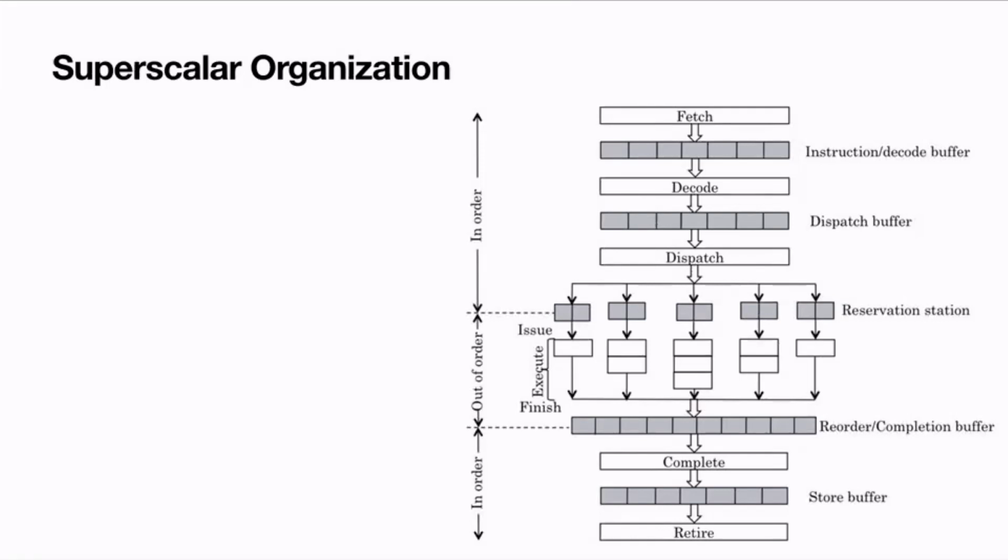Once we schedule these instructions onto the function units, they all execute in parallel, so effectively you are getting parallelization. In other words, the execution time of one instruction is overlapped with the execution time of another, and so on. In a given amount of time, multiple instructions can be executed, and that is the advantage we get with the superscalar.